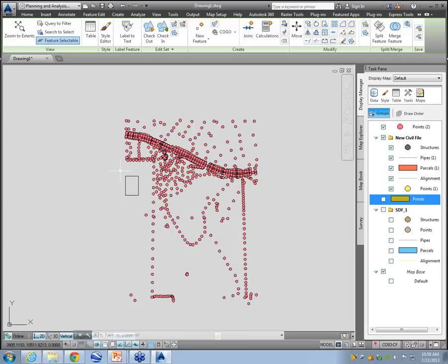So I've been talking a lot about these SDF files, and you all see how we've got all these data tools. So I can add in shape files. I can do a bulk copy of a shape file in here if I want to, just like you saw. You can bulk copy a shape file into an existing SDF file and add a whole new feature class. So there's a lot that you can do.